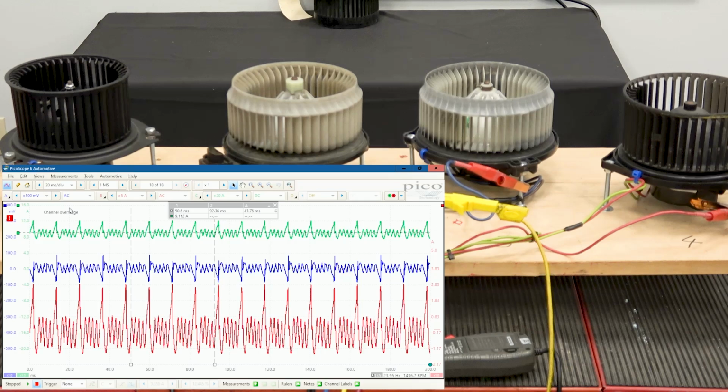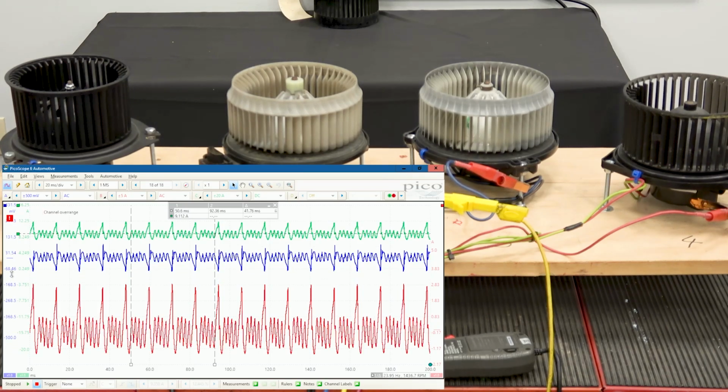Here it's just running in the wide open. The blue pattern, again, is just a simple voltage, plus or minus 500 millivolts, plus or minus half a volt. The point I'm making about the blue pattern is that you could take a simple voltage probe from your scope, AC couple it like you can see here, and you would be able to get a very similar sense of a brush problem in the circuit, even if you didn't have a current probe.